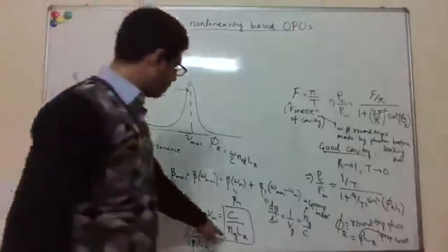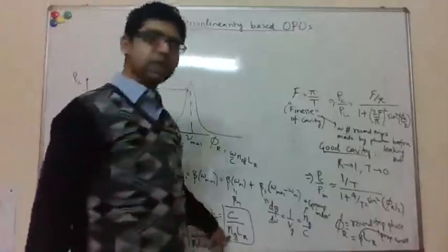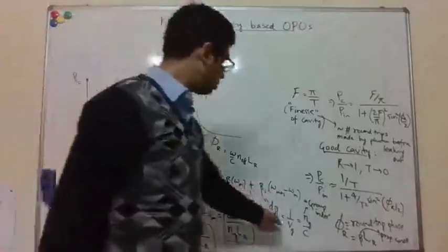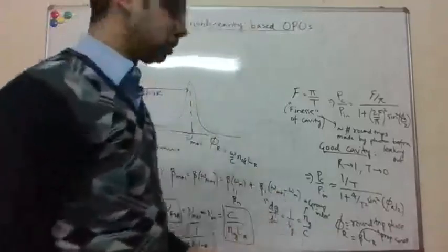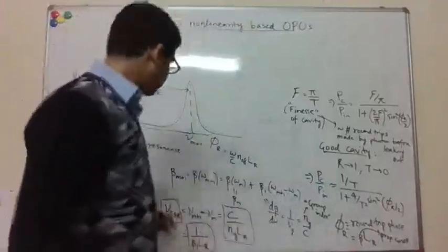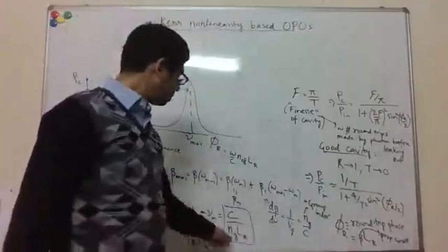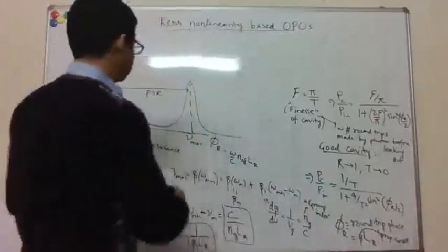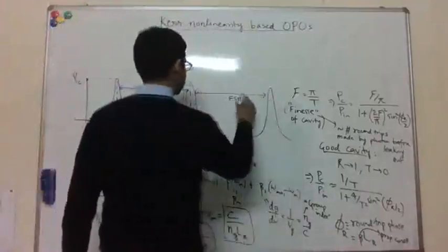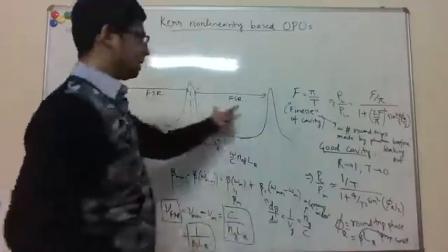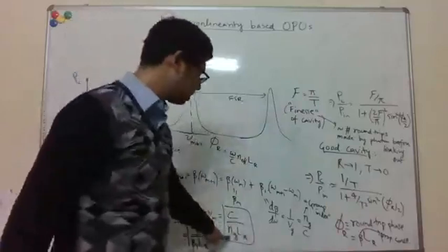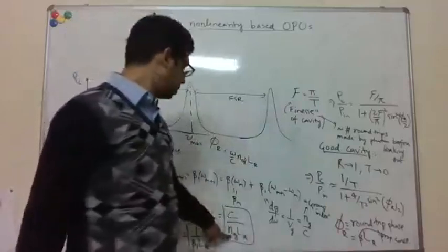So now you can see that if you have a constant group index, which does not depend on frequency, in the cavity, then this FSR is a constant, right? Which means that no matter which two resonances I take, I will always measure the same FSR, right? So it doesn't depend on where I'm measuring, it doesn't depend on the frequency, if this is constant, right?